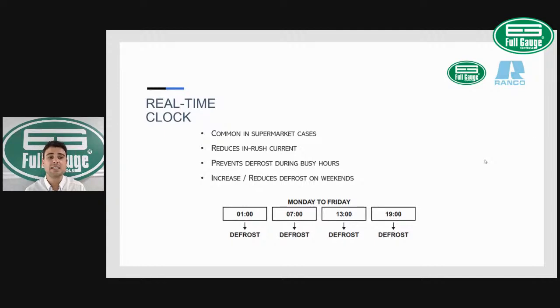So by setting the real-time defrost clock, you can actually reduce in-rush current as well as prevent defrost during the peak hours. For example, there is a restaurant which opens for breakfast and lunch. You don't want your defrost cycles to take place at 8 o'clock in the morning where the restaurant is busy serving breakfast. Neither do you want the defrost taking place during the lunchtime when the restaurant is busy serving lunch.